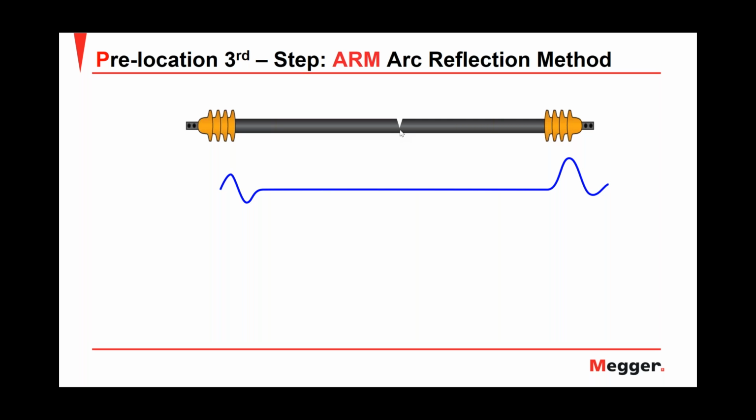Nothing. Nothing will happen, because keep in mind that this fault flashes over at 4 kV, and the low voltage pulse has maybe a value of, let's say, 20 volts. So a low voltage pulse of 20 volts does not have enough energy to bridge the air gap between the center conductor and the concentric in the pinhole in my medium voltage cable. So nothing will happen with the low voltage pulse, and it will continue on its way until the end of the cable.